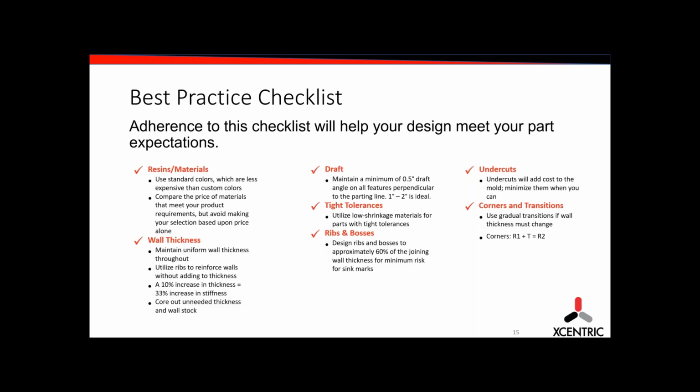Right, and for those that don't know, flashing the parting line is where you actually push plastic out between where the mold halves come together. You're over pressurizing the tool and squirting plastic through the half of the mold. So it's something that has to be trimmed. It may not even be able to be trimmed. It really affects end part quality. So in the end, you want to just minimize those thick areas, core them out, and try to follow the basic rules.